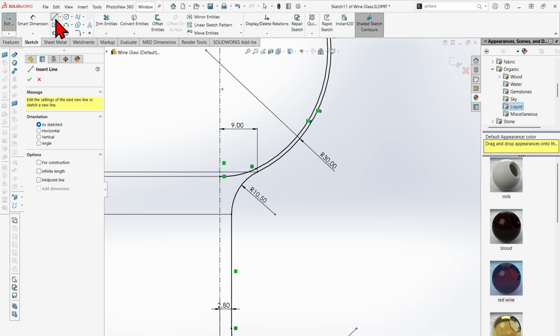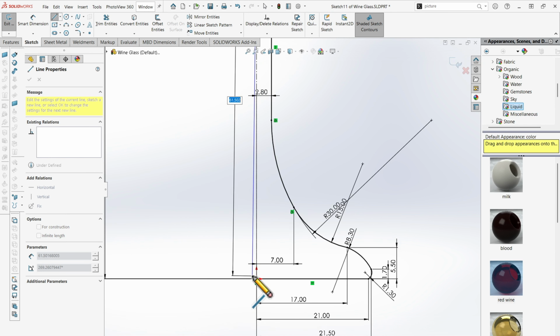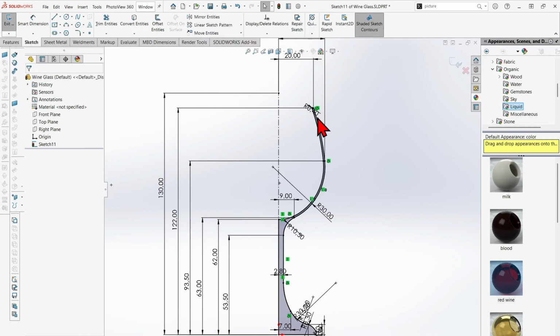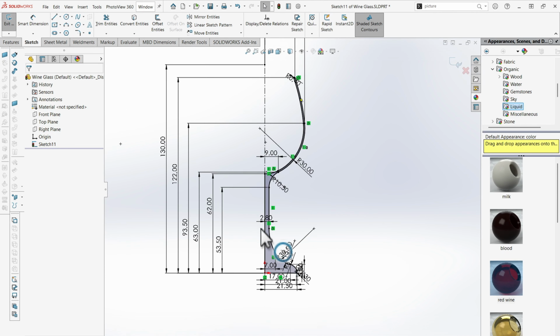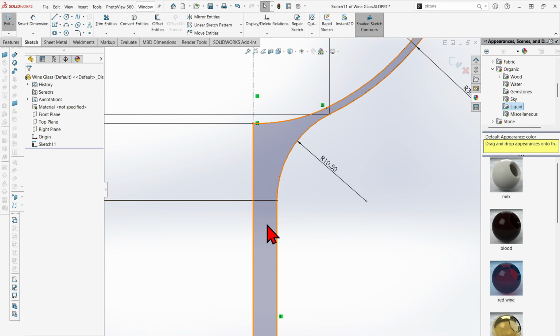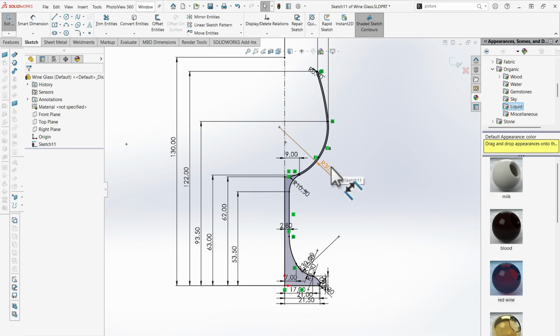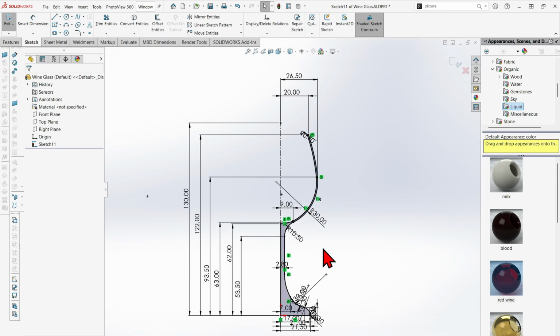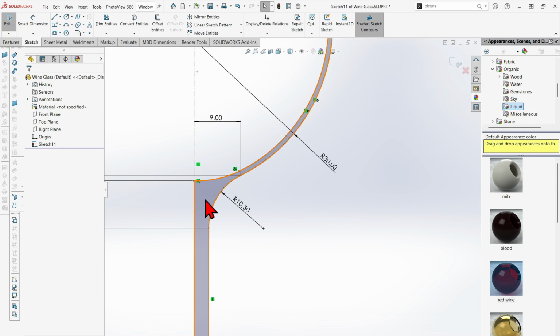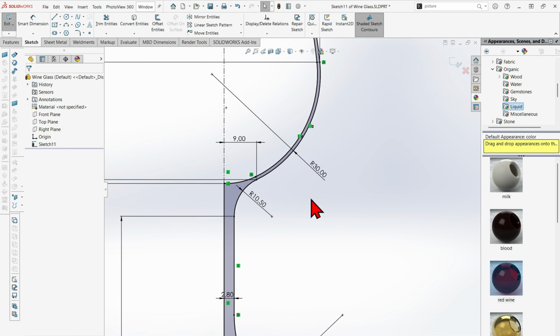What we're gonna do, we're gonna come here, select line sketch, drag it down, and you see what happens immediately after the sketch is continuous from the top, bottom, everywhere. The region in between becomes shaded, and that's the only way you can use the Revolved Boss, because you need to have a shaded sketch or a continuous sketch.